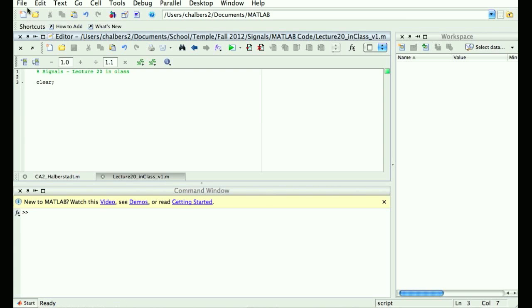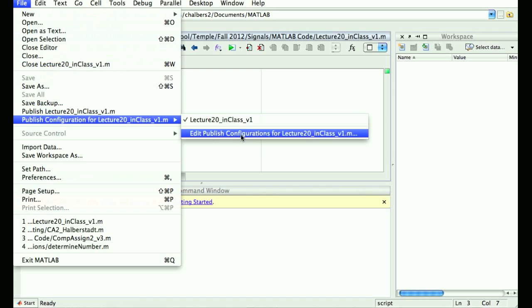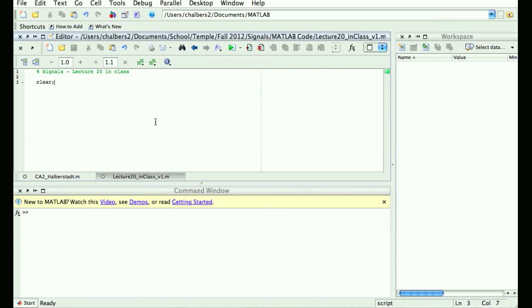Okay, let's do this. Clear figure. Shall we make a filter? I need a value of R and C. In fact, I don't even need separate values of R and C. You can just mush them together in one variable. So how about we say a millisecond for RC? Is good? Glad you agree. So let's take a square wave, a rectangular pulse rather, and filter it. First, let's start by building our filter.